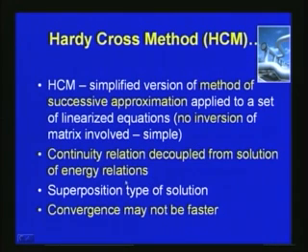The only problem here is that the convergence may not be so fast compared to the Newton-Raphson method, because in the Newton-Raphson method we consider all the loops or all the nodes at a time, but in the Hardy-Cross method we use only one loop at a time.